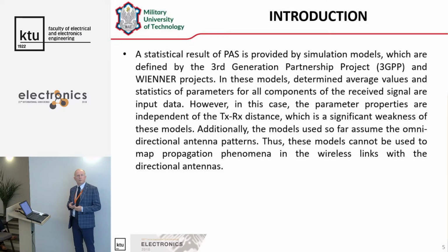A statistical result of power angular spread is provided by simulation models, which are defined by the Third Generation Partnership Project and WINNER projects. In these models, average values and statistics of parameters for all components of the received signal are input data. However, in this case, the parameters are independent of the distance between the transmitter and receiver position, which is a significant weakness of these models. Additionally, the models used so far assumed omnidirectional antenna patterns. Thus, the models cannot be used to map propagation phenomena into various links with directional antennas.